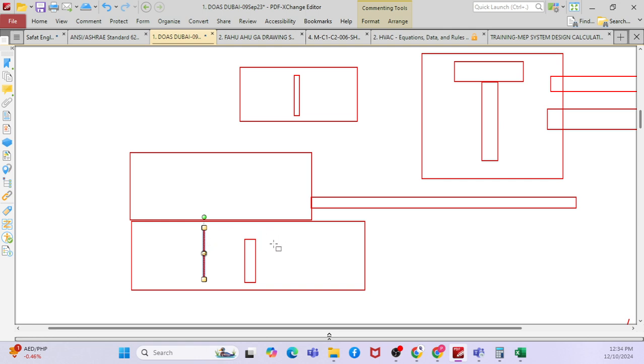So there are different types available to save energy. If you cannot go with the double wheel, or if you cannot go with the heat pipe, then that application is different; you have to go with the one that suits it. I want to save some energy. You can go with the double heat wheel, but it will be very costly, so the client cannot go with that budget. Then they will go with the run-around heat pipe, but the efficiency is lesser. So you have to balance it, whether the initial cost or the operation cost. In that way, they will choose the best fresh air handling unit.